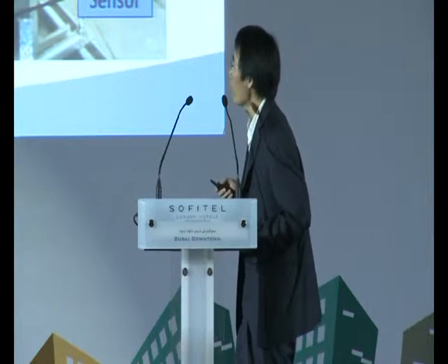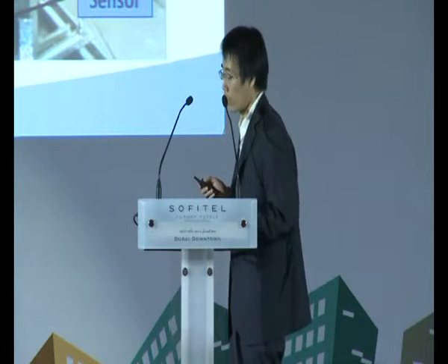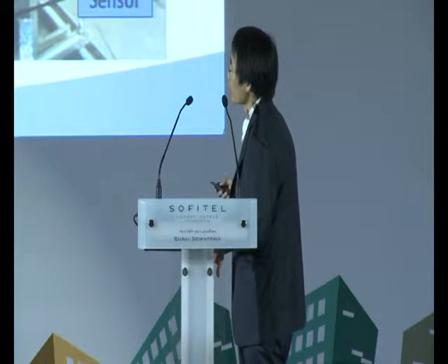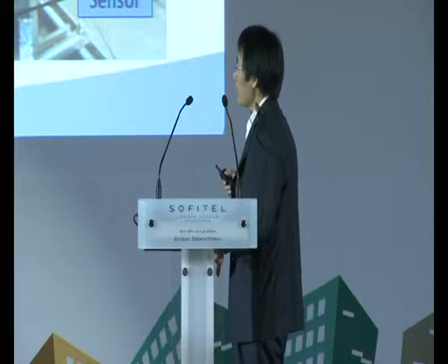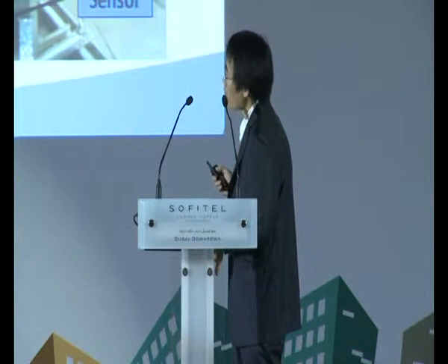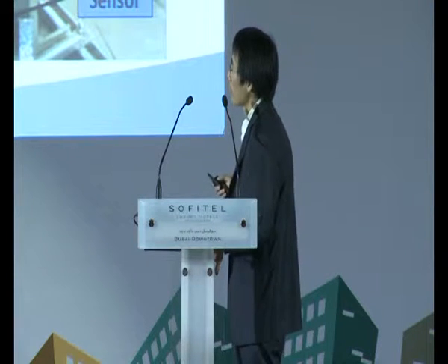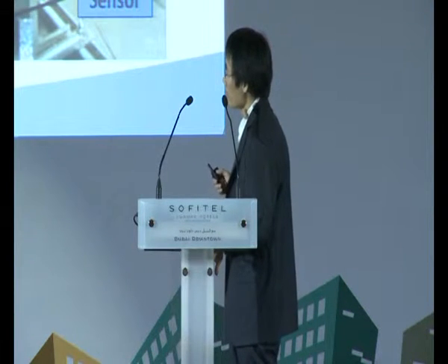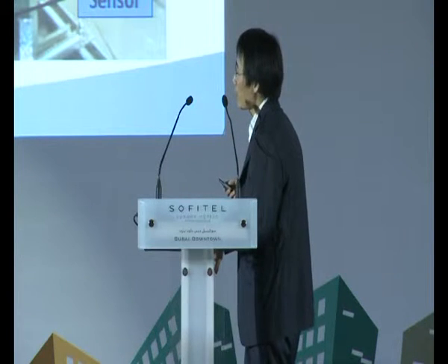As we know, the oil used for R22 has a good miscibility with R290. This would lead to the oil viscosity being very low in the compressor, which will influence the compressor reliability.